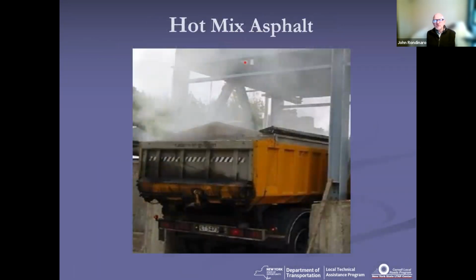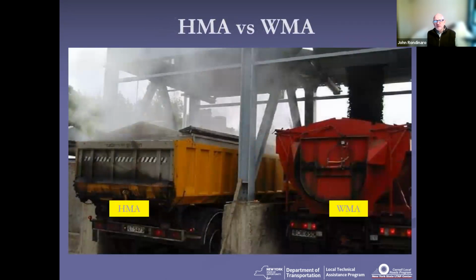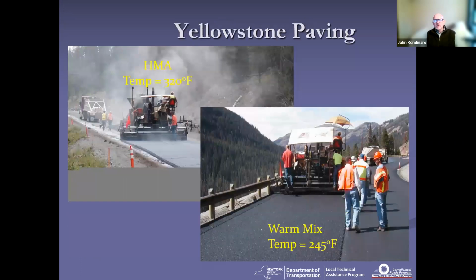Hot mix, this is what you traditionally see when you're loading out your truck. There's a lot of steam coming off the top of that pile. But when you compare hot mix to warm mix, again, you're getting a lot of steam off the hot mix and you're getting almost nothing coming off the warm mix as it's being loaded out. And that's because of the temperature differentials. You can also look at the temperature differentials in terms of your paving itself, your laydown.